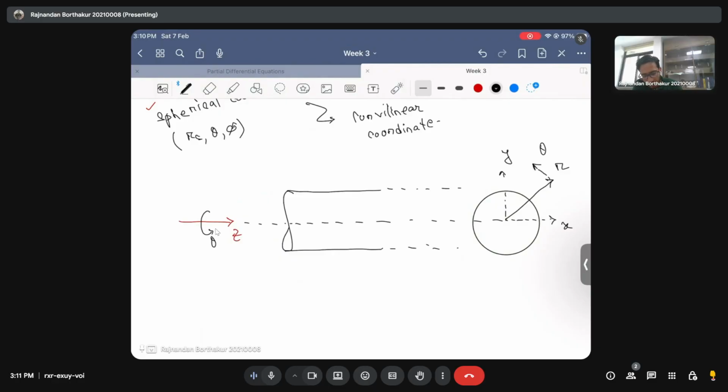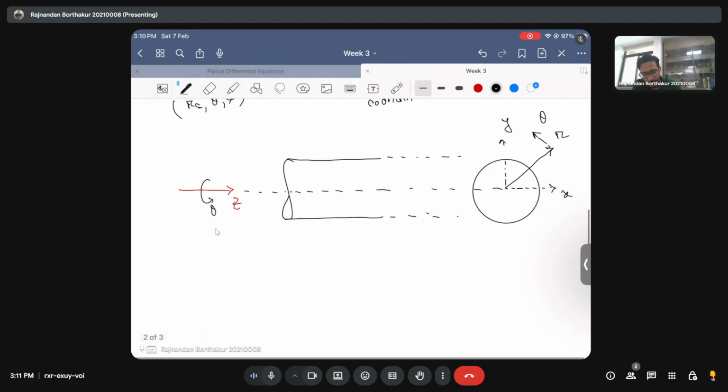Okay. So the meaning of axisymmetry in cylindrical coordinate is that if you move around the z-axis, that is in this form, your variables are invariant, which means in mathematical terms, if let's say v is a variable, then v is not a function of theta. Okay. This is what axisymmetry means in cylindrical coordinate. And this is something that you need to understand when you are dealing with curvilinear coordinates, because it actually simplifies our analysis when we invoke the assumption of axisymmetry.